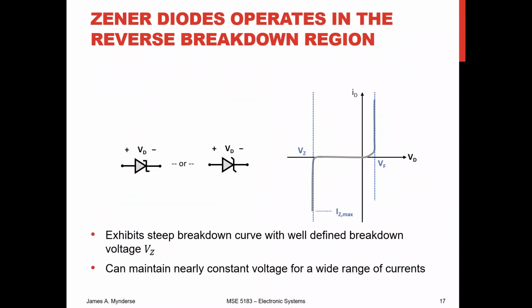Okay, we have very special diodes we call Zener diodes, and so these are operating specifically in that reverse breakdown region where things go negative. And the nice thing about that reverse breakdown region is that you can see, again, the voltage doesn't change very much. And because the voltage doesn't change very much, operating these in that reverse breakdown region is like using a voltage regulator. So why do we call them Zener diodes? Well, because Clarence Zener is the one that worked on these, and so he invented them in 1948 at Bell Labs, and we got to name them after him.